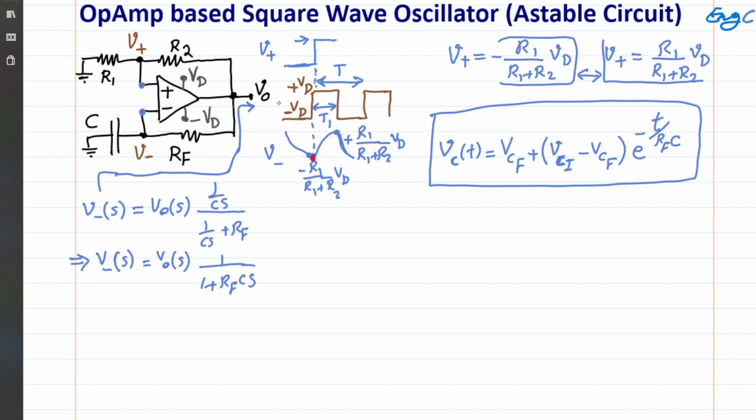You are charging up, and the voltage at the output is VD, and that is the voltage we are going toward. If you had infinite time, the negative terminal would reach VD, matching the output. But in the middle of that process, the op-amp changes its behavior, and therefore things start changing.